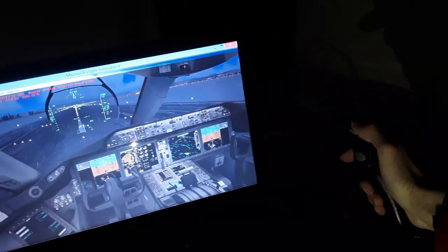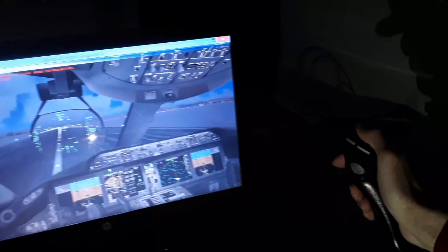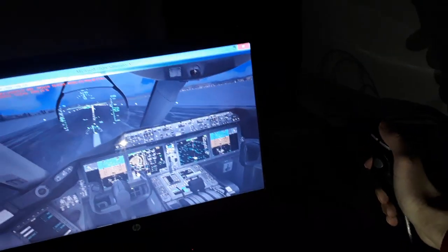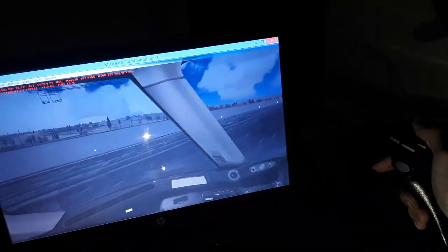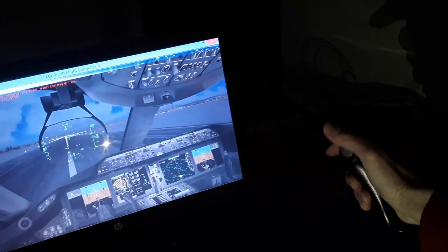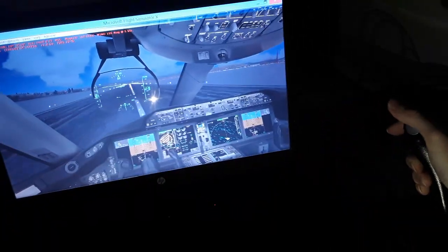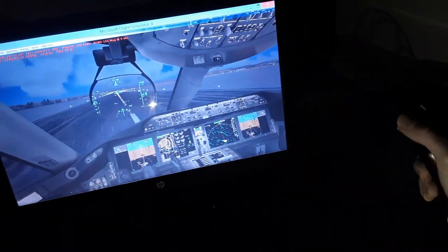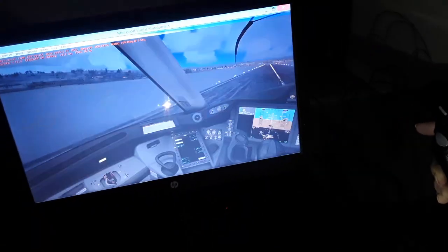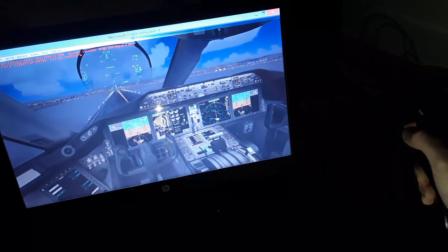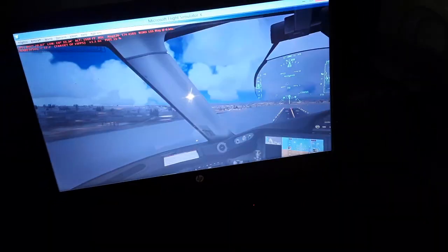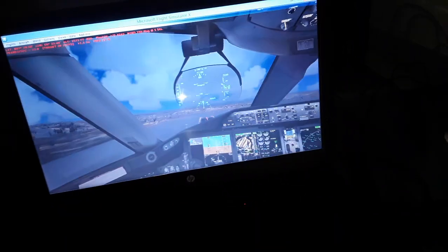So we press the yoke down for takeoff. Align with the rudder pedals also. 100 knots over here. So we have 100, 120, V1, we rotate like 9 degrees, pitch up over here, so we pitch 9 degrees or less the aircraft, and we climb.